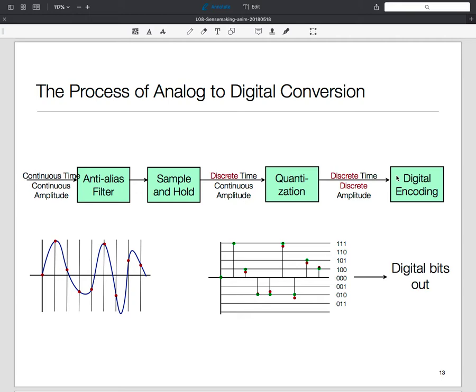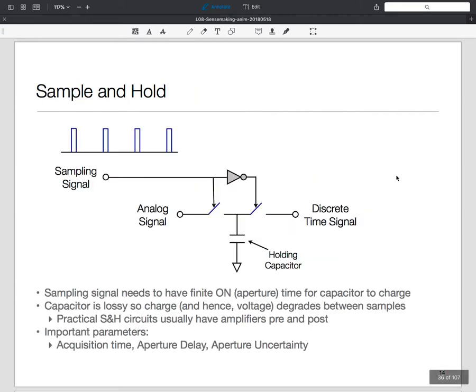and levels far apart in other parts. This is often done with things like speech or sound, because we want to capture the lower levels with higher resolution, and the peaks perhaps you can get away with coarser sampling. The telephone system, for example, uses sampling that is non-uniform, and that's a trick one can often use: you spend your bits in that part of the signal which is more important. So that's what goes on here.